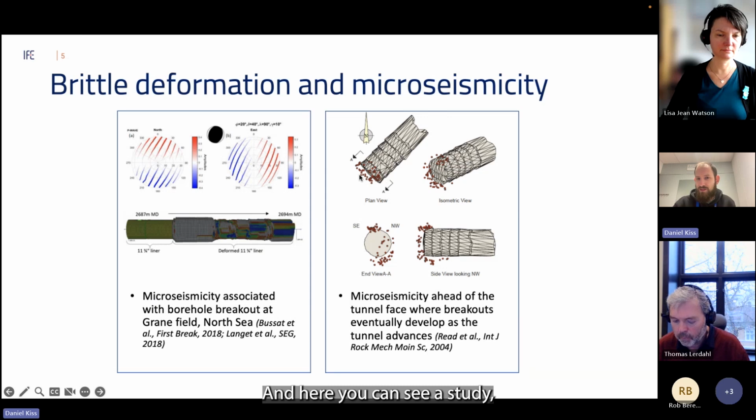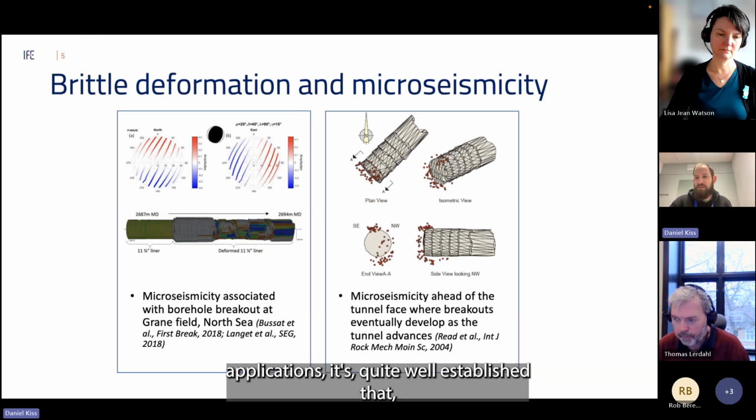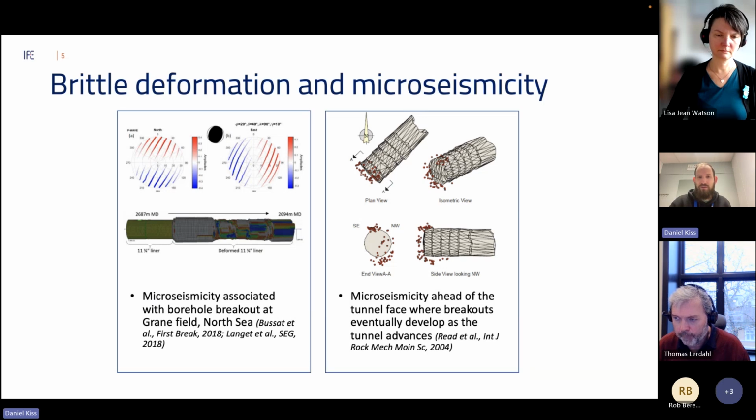And here you can see a study relating tunnel boring with the microseismicity and tunnel breakouts. So in engineering applications, it's quite well established that microseismicity is a good precursor of any sort of fracturing.